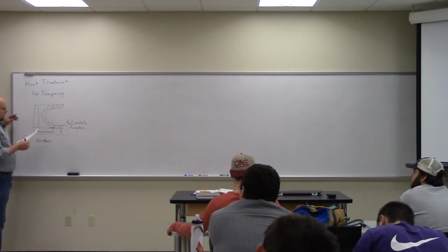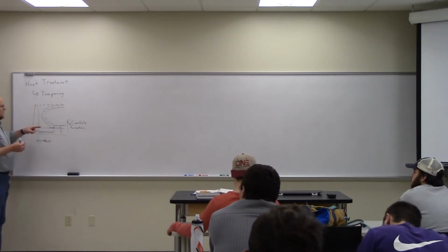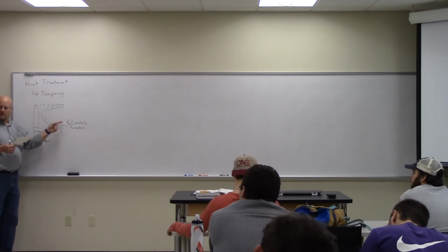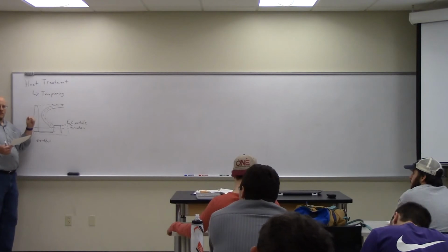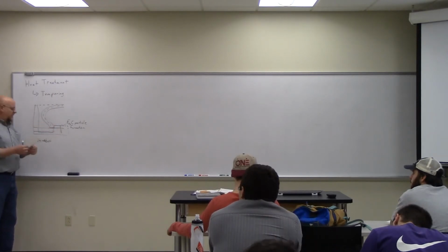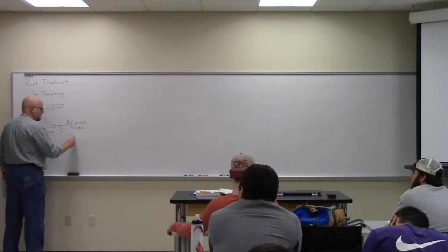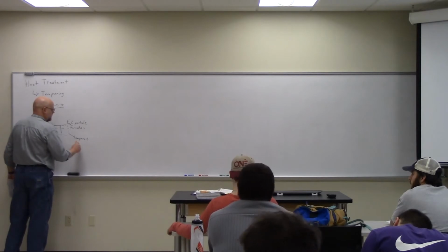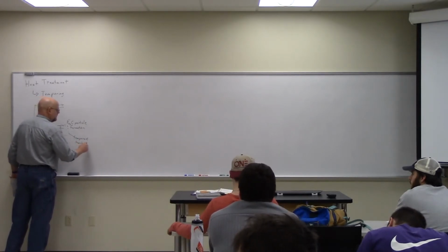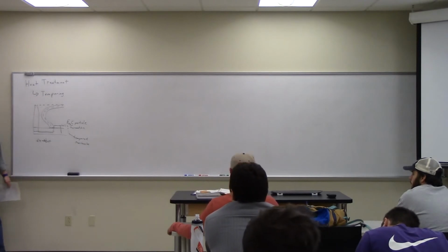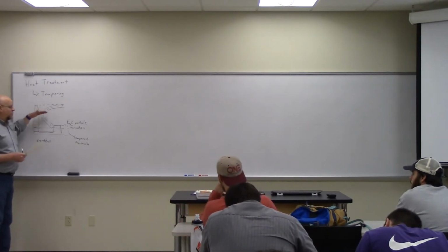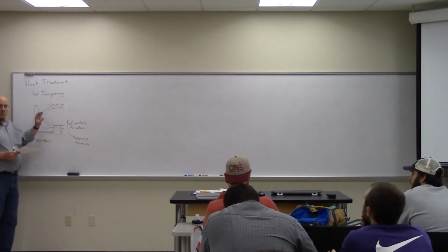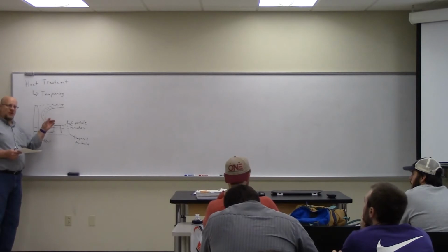And so what happens is, the strain relief allows you to regain some measure of ductility in the martensite. So this would be tempered martensite. The thing you would end up with out here is tempered martensite. Okay. So in this case, we've actually softened the material a little bit. We've returned some ductility. But we do so by changing the nature of the microstructure.